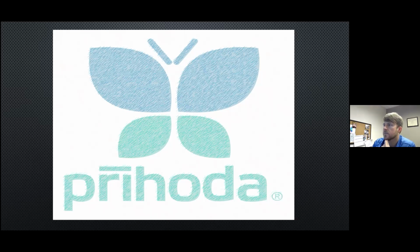So the next question, does air distribution take advantage of the Coanda effect? Yes, absolutely. That's sort of the basic idea, using the Coanda effect. A really good example is that indoor swimming pool project that I showed the pictures of, with the control pockets turned 90 degrees. That's using the Coanda effect, moving that air across that ceiling panel that was designed in, so that we're getting further air distribution off of that system.